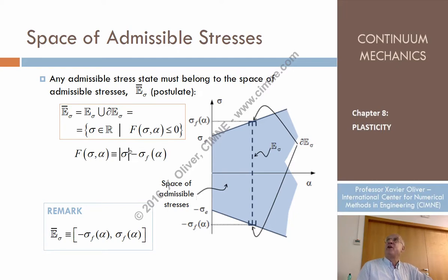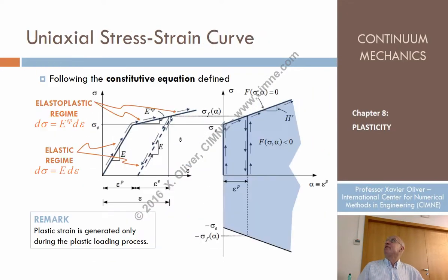It is the derivative of the modulus of the stresses with respect to the stresses. What is the derivative of the modulus function, modulus of x with respect to x? Imagine that. When x is positive, it is 1. And when x is negative, it is minus 1. So it's the sign of sigma. So look, the derivative of f with respect to sigma is the sign of sigma. What do we have here?